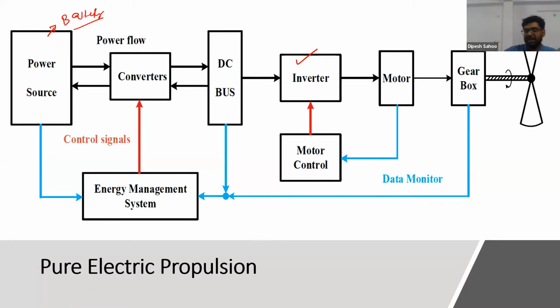If we want to have extensive control on the motor or rotation of the motor, then the motor should be a two-phase or three-phase motor. But our power source is only a single phase. Hence, we need inverters to convert single phase to three phase.